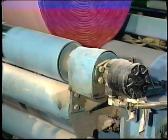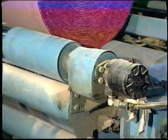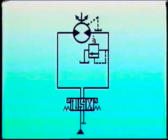Whenever hydraulic motors are braked, some method must be used to make sure fluid is available at the motor inlet. If this is not done, the motor will cavitate and may be damaged, just like the pumps we saw earlier. Three methods are generally used to ensure that the motor is continually supplied with fluid.